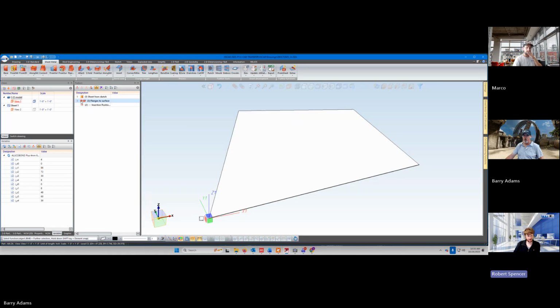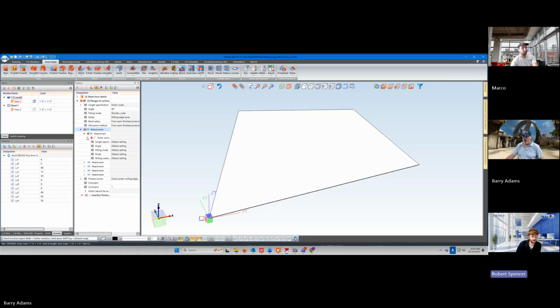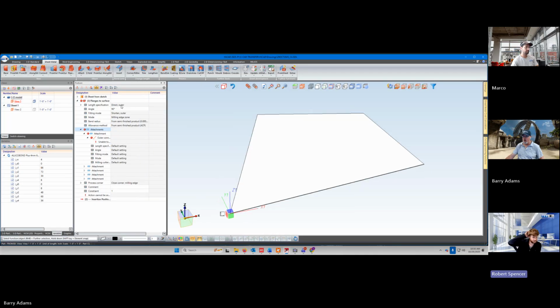Action cannot be executed. If you expand your feature step, it'll tell you what the error is. You see how it's an attachment? So expand that. Sometimes you have to dive for it. And this one is probably going to say edge not found or something like that. Okay, unable to find edge.